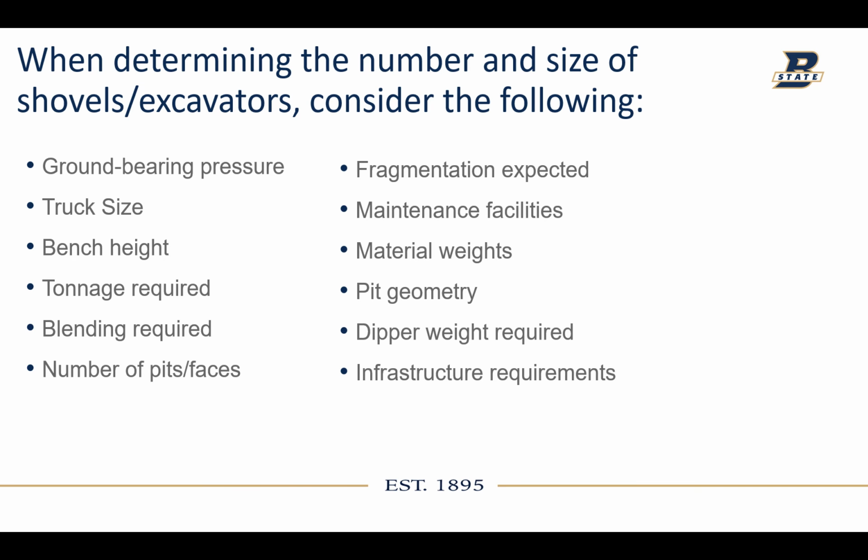When determining the number and size of shovels or excavators, you have to consider the following 12 parameters, okay? That's the ground bearing pressure, the size of the truck, the bench height, the tonnage that's required, whether or not you have to blend your materials, the number of pits and faces, the fragmentation that's expected, like how good your fragmentation is, what maintenance facilities you have, material weights, how much it has to pick up, pit geometry, the dipper weight that's required, and infrastructure requirements.